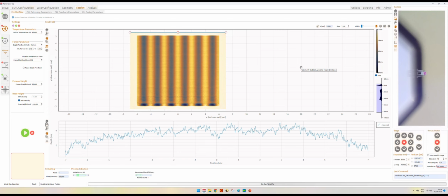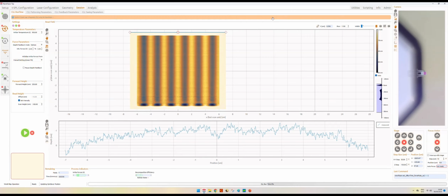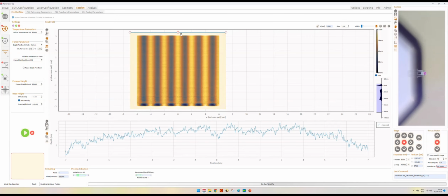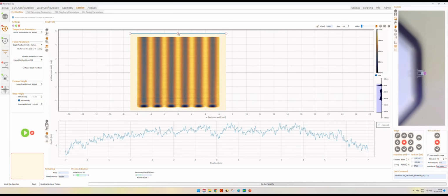We may expect that if we increase the contact time, we are increasing the energy that our substrate, which is coated by PPA, receives. More thermal energy received means more material being sublimated, so larger depth of patterning.